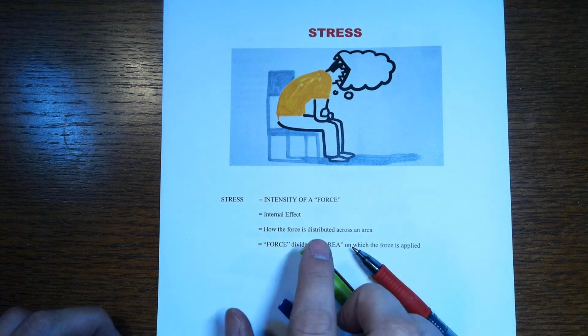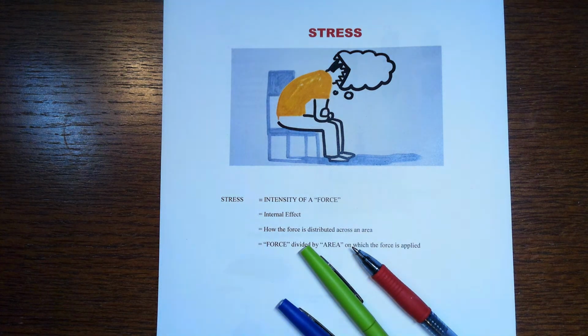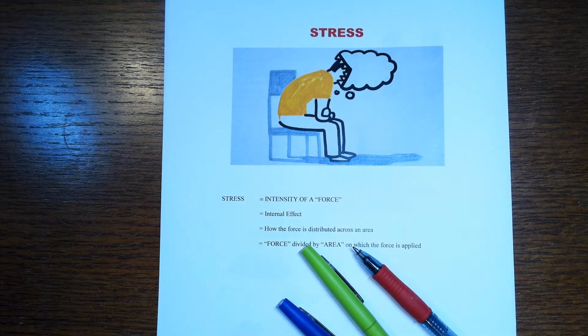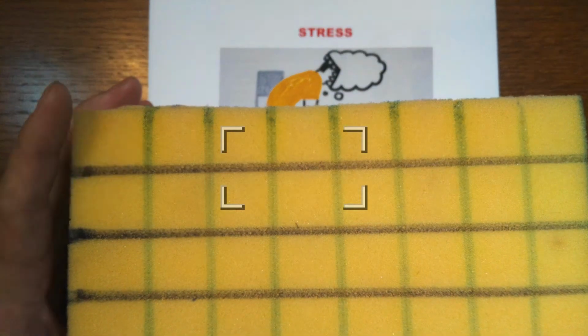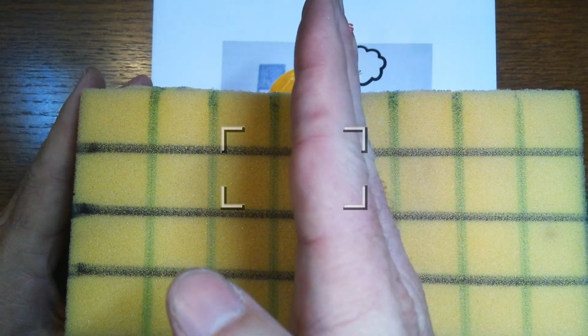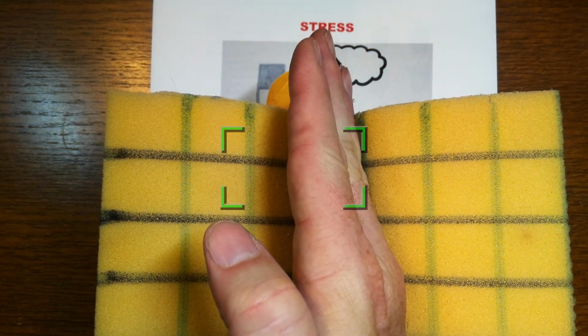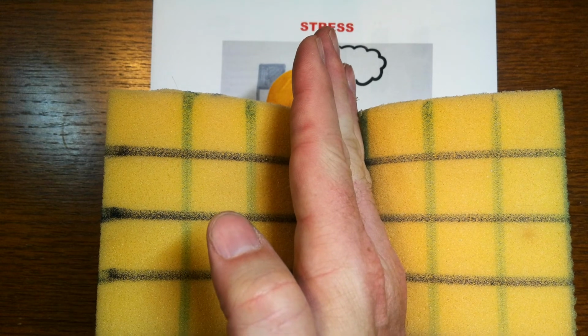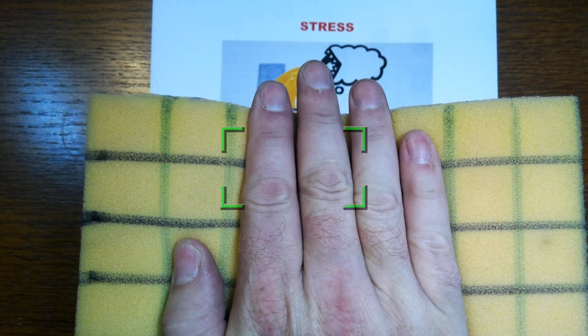This notion of stress is something about the intensity of a force. It's not how you feel right before an exam or dealing with difficult professors. Here, take this little sponge block, and I've got this grid set up. If I apply a specific value of force, but over a very small contact area, so that would be a contact stress, notice there are much different deformations that result than if I take that same force and spread it out over a much larger area.